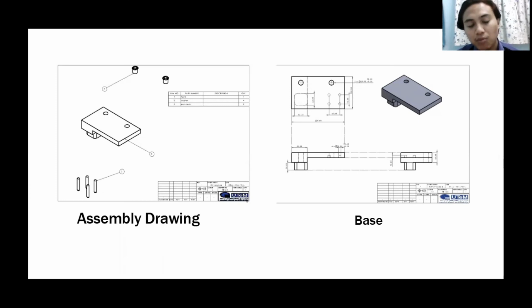That means the Poka-yoke concept, which is the locator and the Poka-yoke in our base template, is to prevent any misalignment and prevent the workpiece and the template from moving during the drilling process. The function of the bush in our design is to ease and guide the manufacturer in the drilling process.